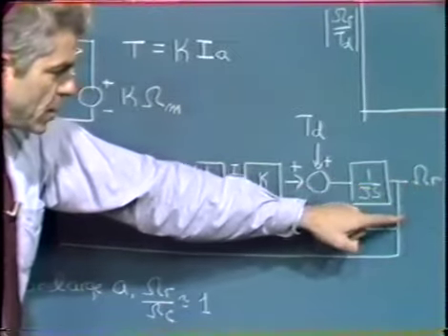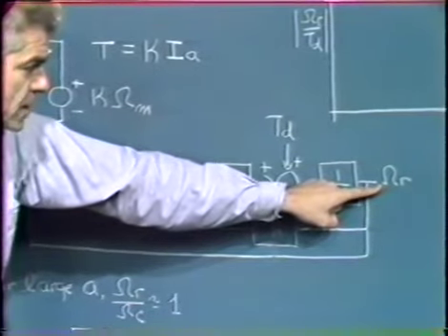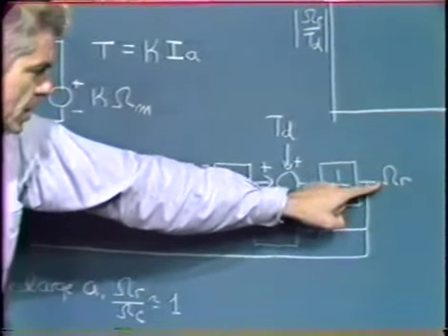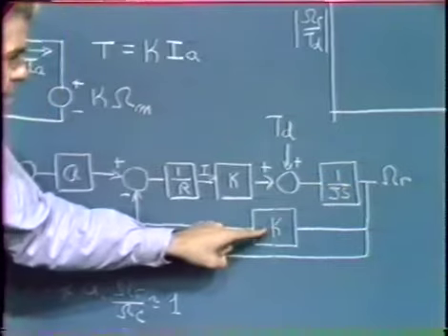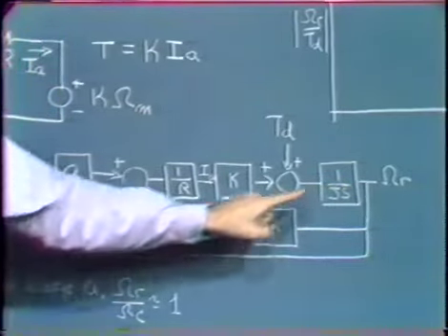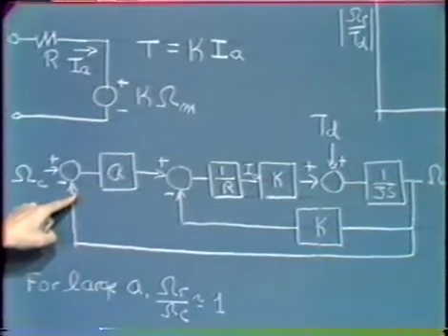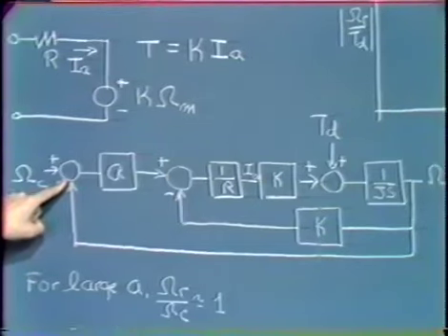Once we've gotten to that point in the block diagram, of course, we have the variable necessary to complete the various feedback paths. We multiply motor velocity by our constant K to get the back voltage associated with the motor. Similarly, we bring back velocity information, probably via some sort of a transducer, as I mentioned earlier, a tachometer, to the input of the system.